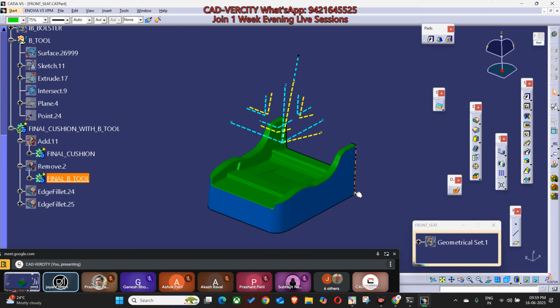No, no. We have some density for the PU. As per the requirement in the project, we control the hardness of the foam with respect to density. If we control the density of the PU, we can control the hardness of the foam. So we will never do any extra process on the foam. Yeah, we will have the wire inside the foam.